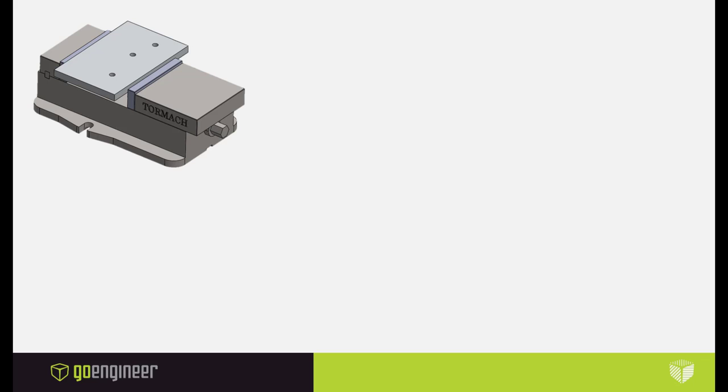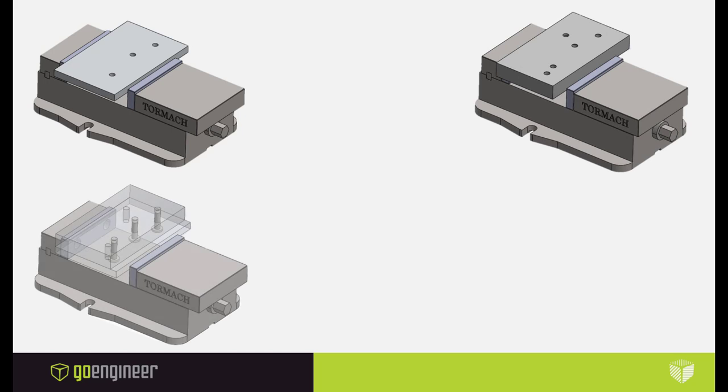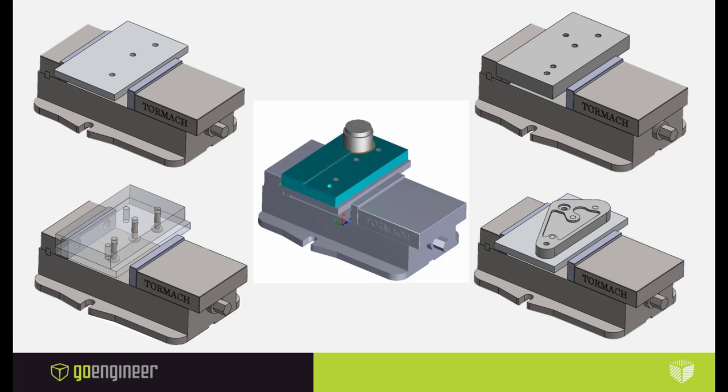It involves using a fixture plate, which the part will be fastened to. The first step is to drill the holes in the fixture plate, making sure they accurately align with the stock. Then drill and tap the holes in the stock. Then I can pass the screws through the fixture plate and screw them into the tapped holes of the part to fasten it securely to the fixture plate. This method allows me to machine all the features in the first setup, as well as the second setup to complete the part. I want to show you what the process looks like using Solidworks CAM.